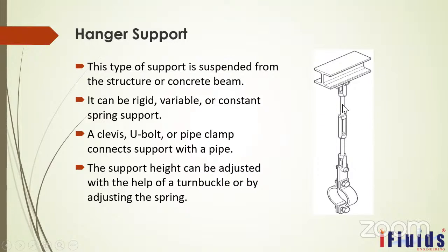Here one stud will be there, and here another stud will be there. Based on the pipeline height, we can adjust this turnbuckle and locate the pipeline. This kind of hanger support will be preferred where there is no space for a bottom support, or where we need more manned areas or more space for maintenance. Those kinds of areas we can go for this kind of hanging support.